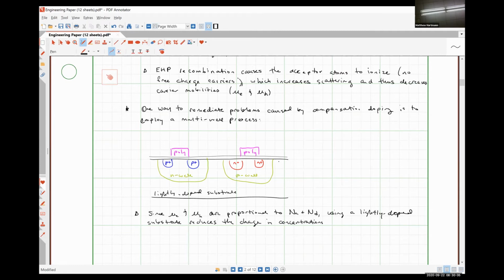We're going to create what are called Schottky diodes everywhere we try to electrically connect to our substrate. Because we want our substrate usually to be grounded. And if our substrate isn't conductive, we are going to effectively be unable to properly ground the substrate. Does that make any sense to you? I think so. Okay.